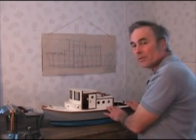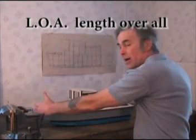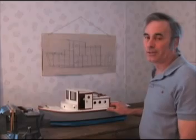The main measurements on a boat will be the length overall, L.O.A., and you'll see that on plans, which is the maximum length of the boat with everything on it. And it's what the marina will measure when they charge you for a slip. It will go from your anchor, if it's on an anchor roller, to the end of your outboard motor when it's raised. It's the maximum length on the water that the boat takes up.